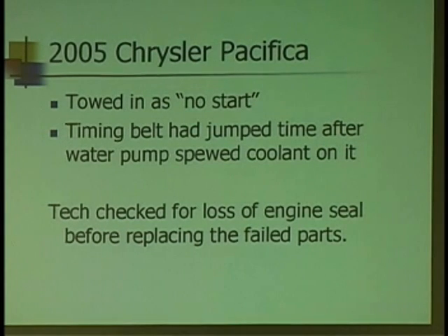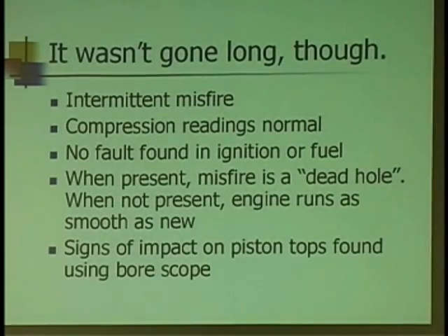The tech who worked on it, very competent man, found very quickly the timing belt had jumped, the water pump had failed. So he checked the engine over, it looked like everything was still good and tight, didn't suspect any damage to the valves. Put a timing belt and water pump on it, fired it up, ran beautifully. Turned it back over to the customer, and about a week later it came back.